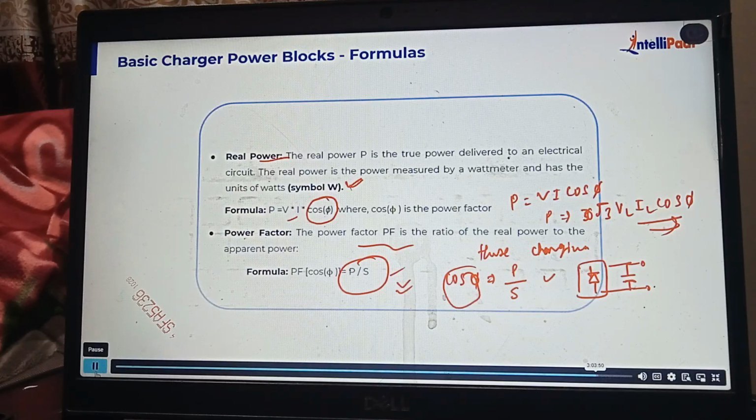What is the power factor of this? So power factor is not simple P by S. Here the power factor is changed because we have some harmonics in this system. So power factor is changed to distortion factor and fundamental power factor. The fundamental power factor will be unity, but the distortion factor will be 0.9, 0.8 like that.